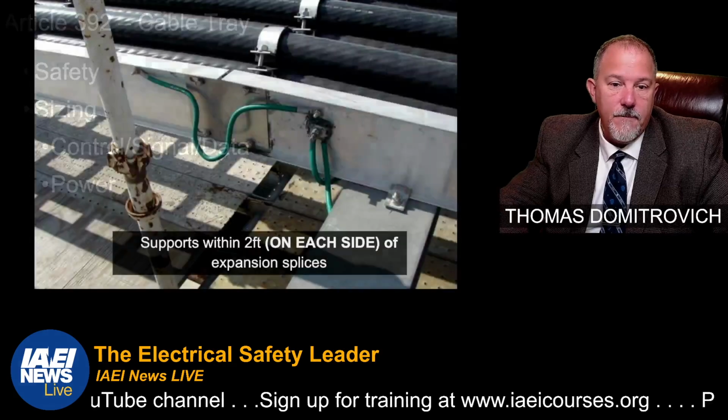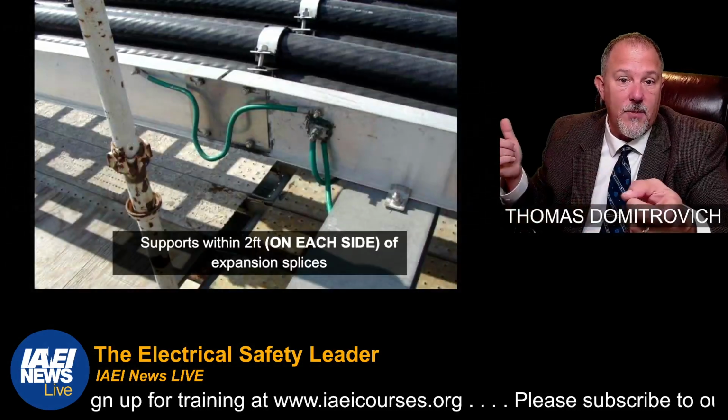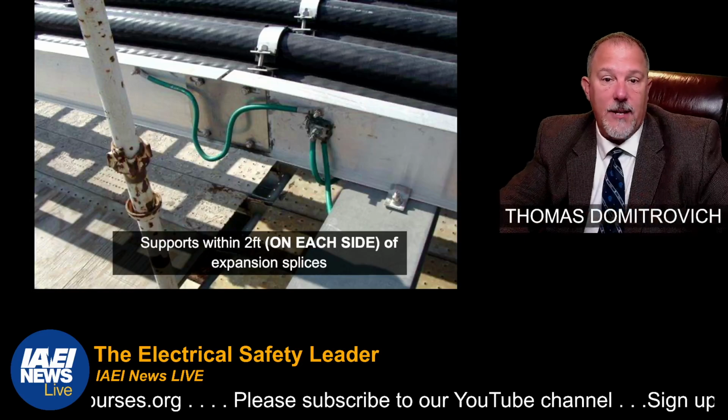Within 2 foot on each side of the expansion plate. So this one here is a bad example. This one does not have a support within 2 foot on each side of that expansion plate. It's only on the one side.